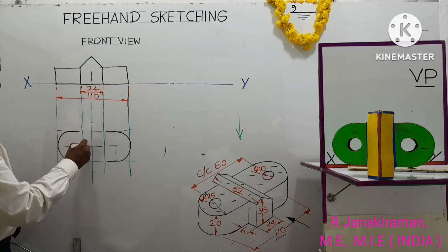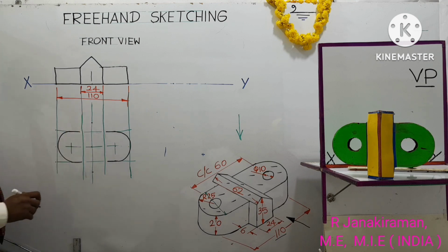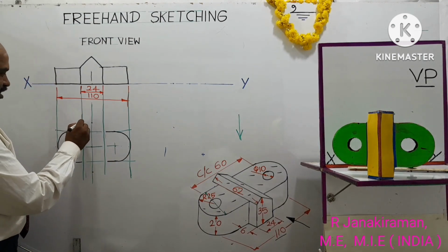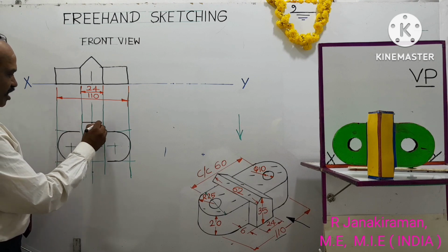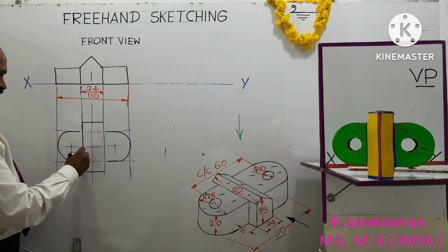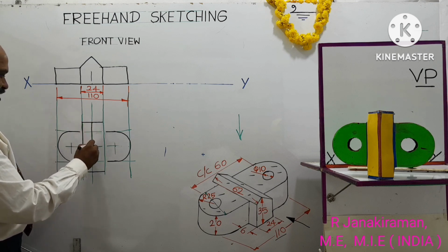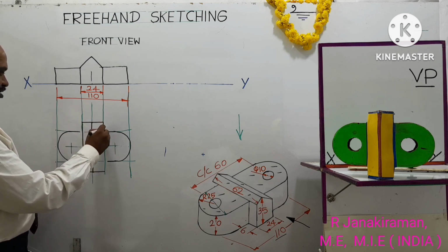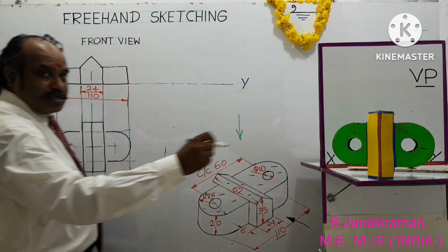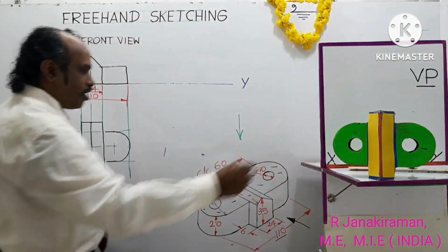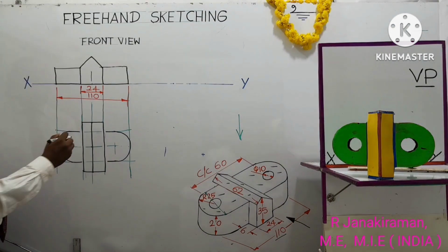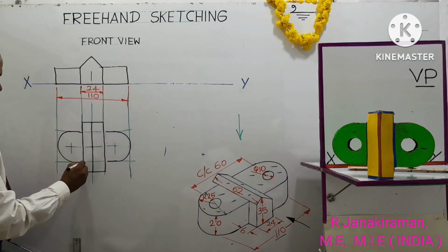Similarly on the left side. Okay, so here using an HB pencil, draw the object lines showing the edges. Here we located one point; there you draw a horizontal line. Below also you draw a horizontal line. Enclose this inside a rectangle. This center line is drawn with an HB pencil. So this center line edge represents this red color edge, the top edge. That is, this is that edge. Okay, extend these horizontal lines.